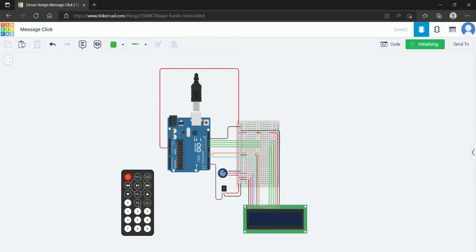The input is mainly given to the number buttons 0 to 9 and sent to the string using the forward button. Each letter has an input value like 1 for A, 2 for B, and so on. In case you make a mistake in the input value, press the ST/REPT button to set the value of input to 0. If you press forward with 0 input, it adds a hyphen to the string. Numbers can be added too, with input value 50 greater than the number, like 50 for 0, 51 for 1, 52 for 2, and 53 for 3.